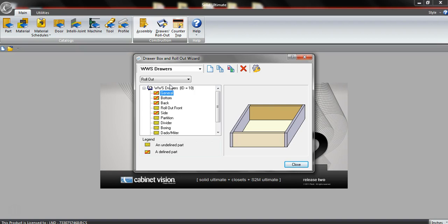Hand drawn, you just have to think about every little detail. Every little opening. You take an opening, add 1.5 inches for the overlays, minus 1/8, divide by 2. It's just a lot of calculator work that'll catch up. And the same applies with the drawers, the rollouts, all of it. It'd be a giant pain in the ass.